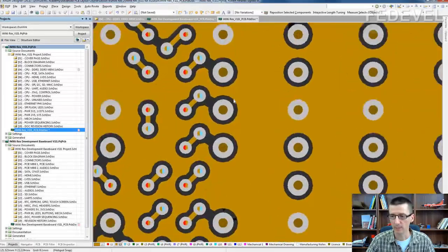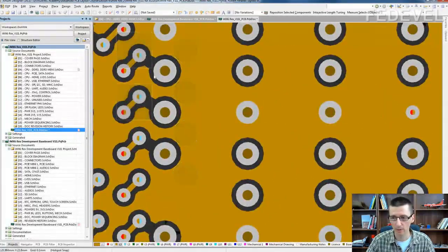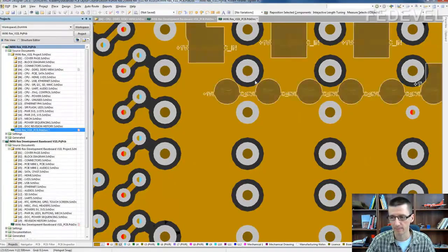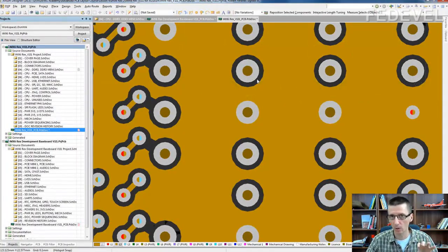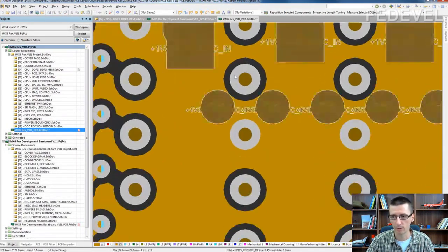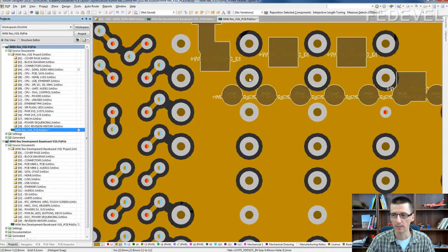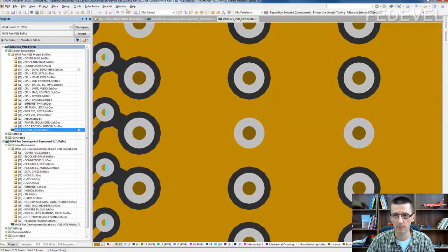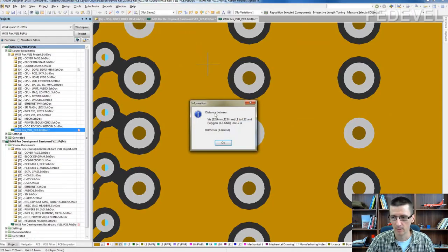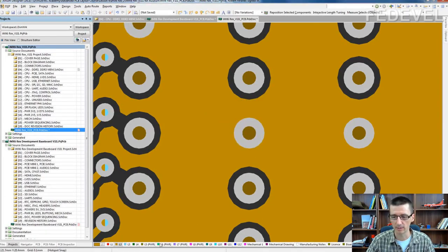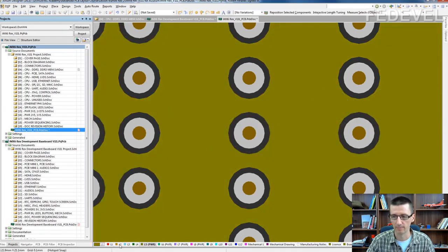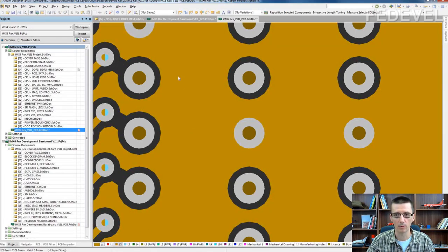And again, as before, we can improve it again. We can improve the smaller gap even in the areas where the through-hole vias are used, because this copper around through-hole via will be removed during the PCB production. So we can safely change this gap, which is now 0.085, to 0.075 as on these other layers which are here. So let's create one more rule.